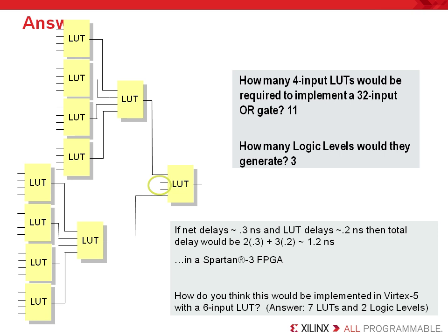Well, thanks for trying your best. As you can see, you should get something like this. Wow, that's a bunch of LUTs. In this case, 11 total LUTs. But note, only 3 levels of logic. This is because the second and third layers can quickly group the logic for the best result.